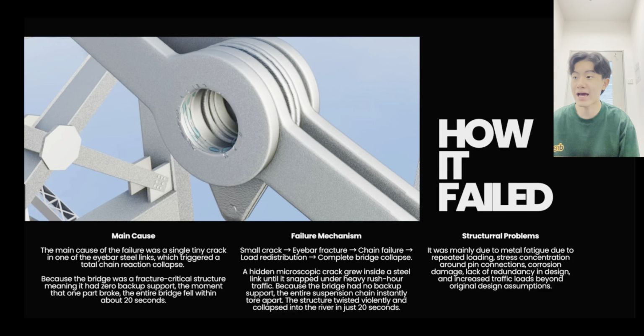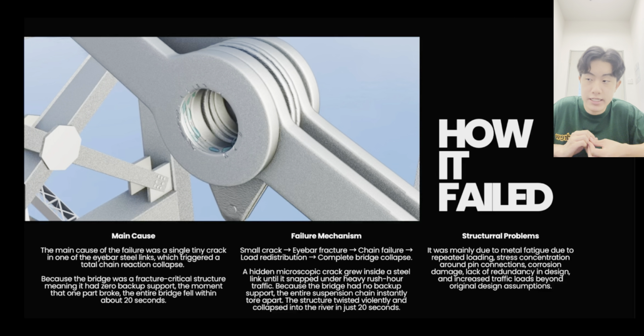Which means every time vehicles cross the bridge, the I-bars experience a cycle of loading and unloading at the same time. This repeated stress gradually weakened the material through a process known as metal fatigue. And you may ask, how does metal fatigue cause such a big collapse, right? Metal fatigue occurs when a material is repeatedly stressed over a long period of time, which causes small cracks to slowly grow even when the applied stress is lower than the material's ultimate strength.